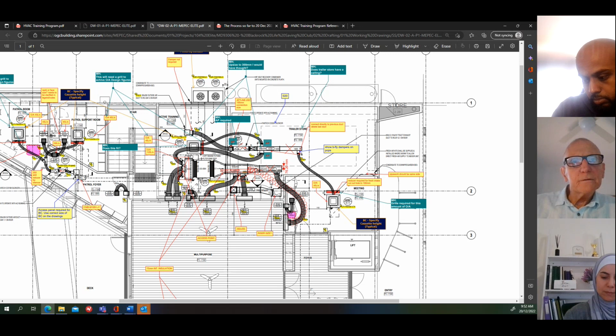I was just saying to Jalen that when ductwork is made, these straight pieces of duct are usually made from a 1500 wide, what's called a coil. It's a coil of sheet metal which rolls out through a machine and gets formed into a duct, and the ends are turned up to make the flanges, and it finishes up being 1400 long. It starts at 1500 and finishes up 1400. So that's something worth knowing.